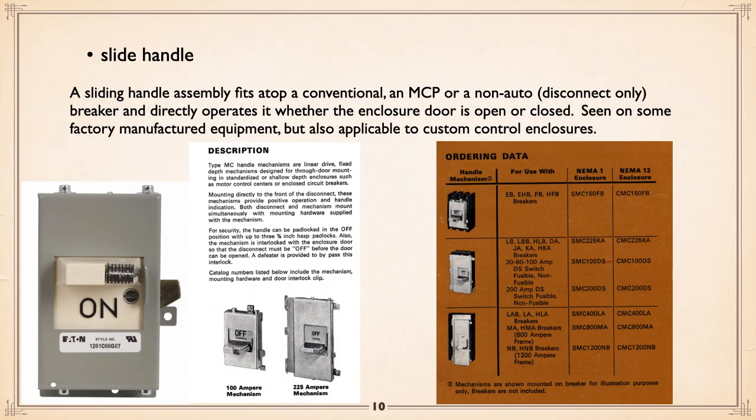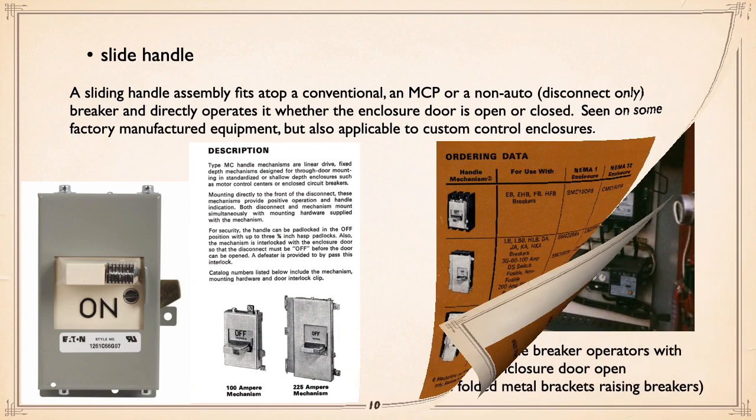This is actually something that Westinghouse, which became Cutler Hammer, which became Eaton, developed, and I'm a big fan of, and I think they're still around. Basically, what it is, it mounts right on a circuit breaker, not a switch, but a circuit breaker, even if it's unfused. It mounts to it, and when you open the door, it is still there. It can be tripped back on if you want to test for current, but if you have to kill it, bang, you can do it very quickly just by slapping the top of the handle.